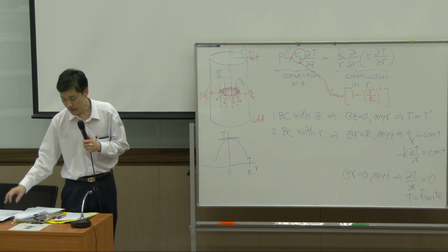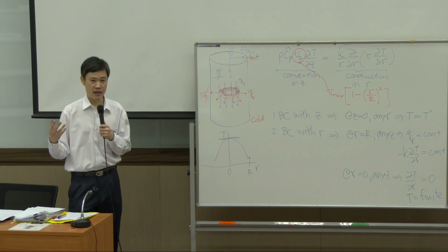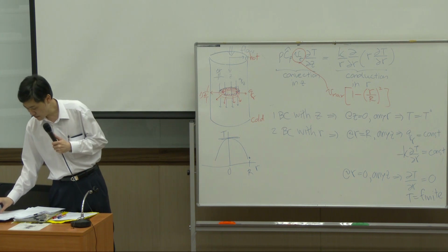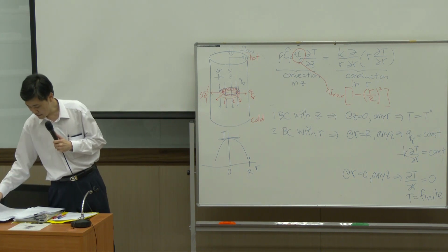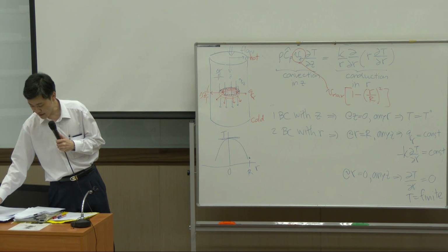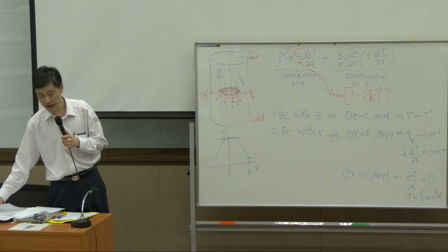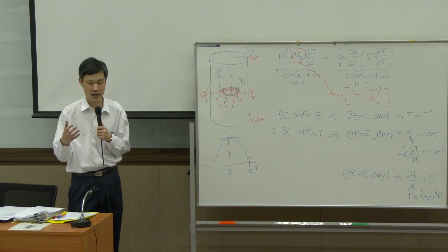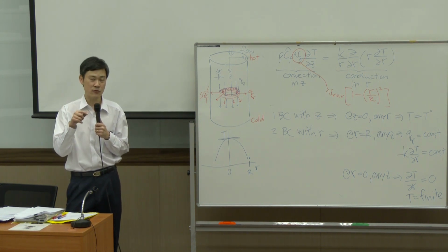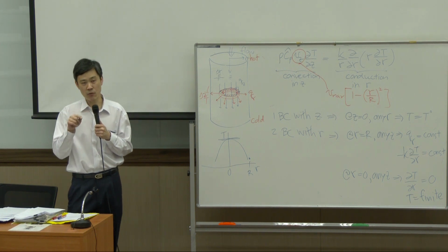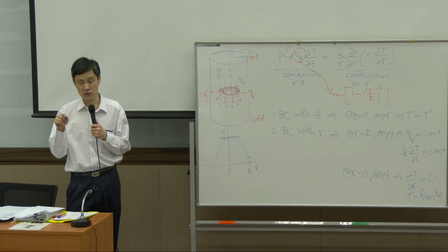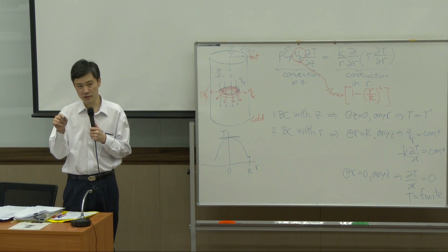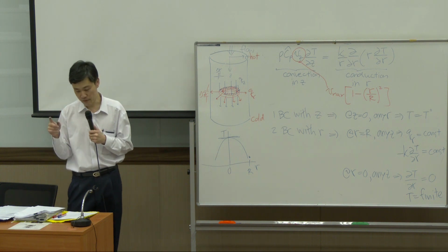The viscous heat example is the first example that has momentum and energy transport at the same time. We allow fluid to flow. But in that particular example, convection is not as important as the flow work. So we drop the convection term, we use flow work and calculate the temperature profile.